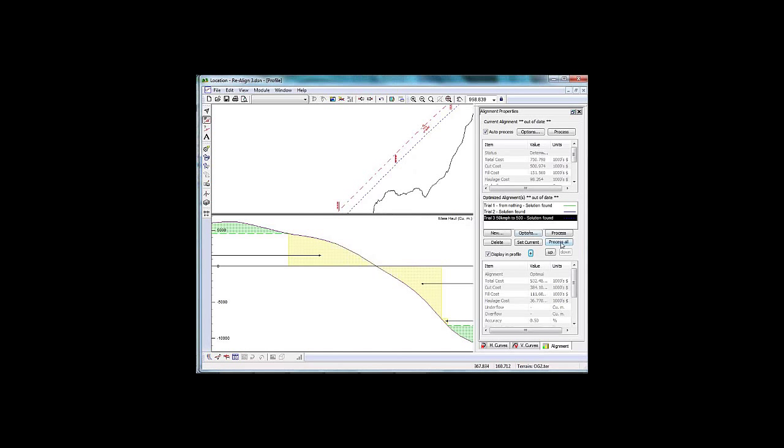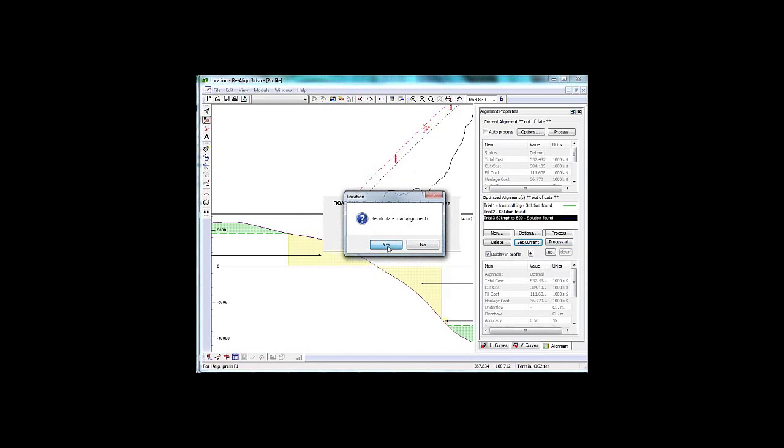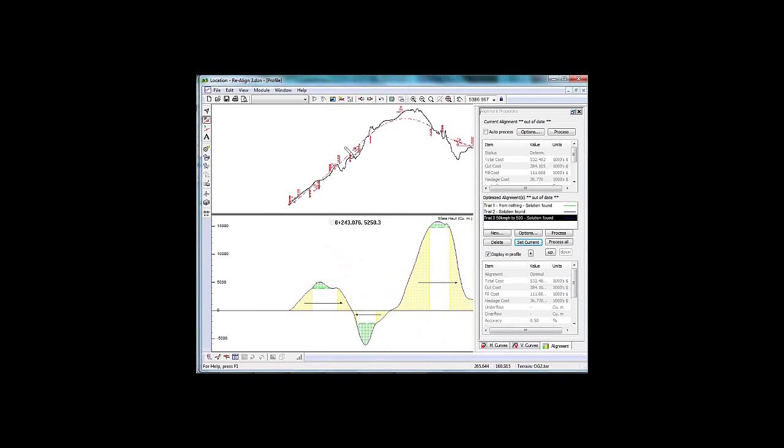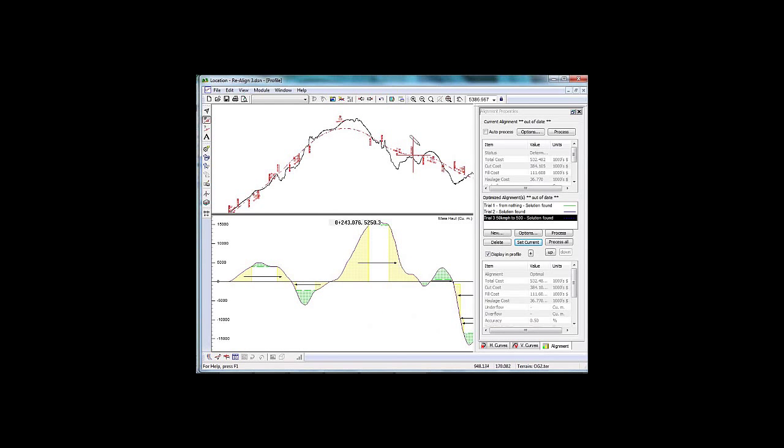In that vertical alignment, you can set that current, and you can now print it out as a design. We're working within RoadEng here. RoadEng has the ability to print out your plan profile sheets, save as LandXML, export to DWG. We're ready to design. But one of the things that the optimizer calculates is haul.